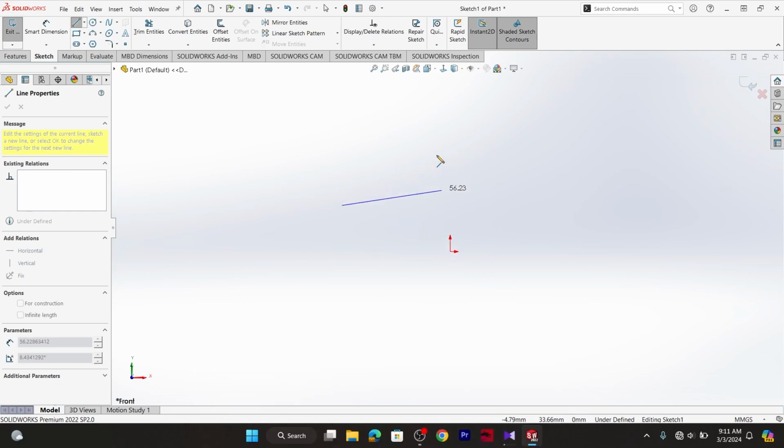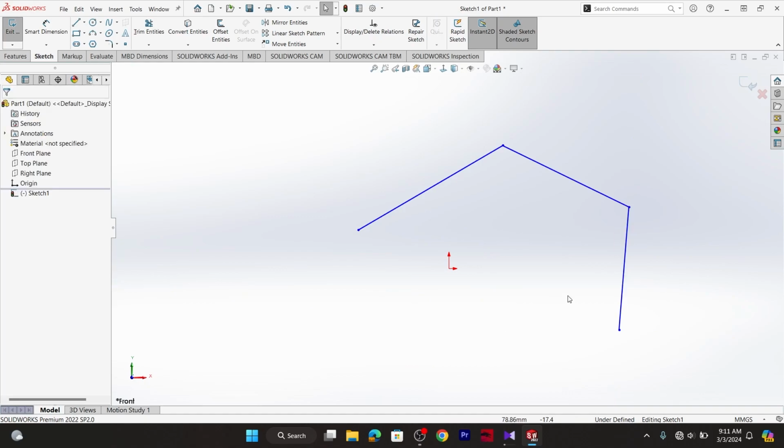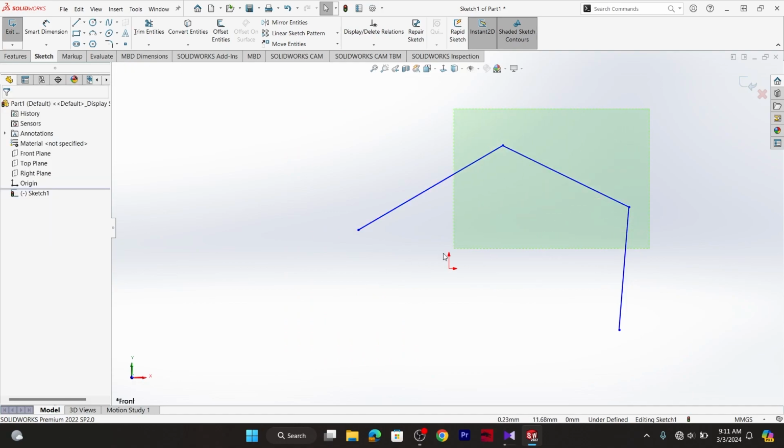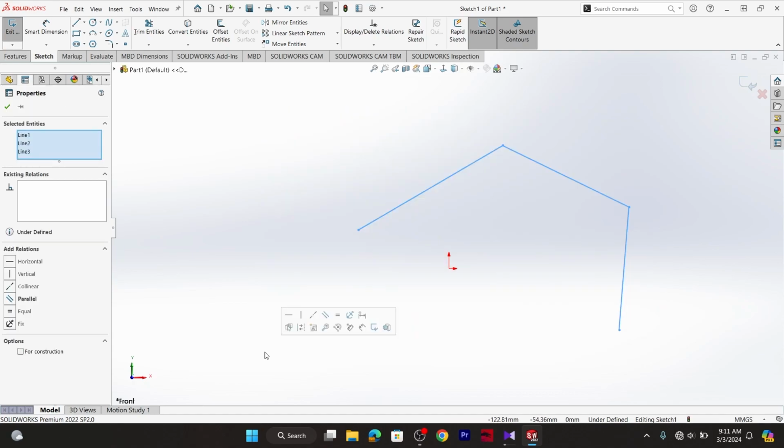If you click and hold your cursor, you'll still get a line, but it's not the required kind of thing, so you can click, let go, then again click, again and again, and you'll have your lines. Now, once you're done making your line, you can press the Escape key to exit out of the line command. Now let me select it all, and to do that, I'll just make a box. So this time I'll click and hold my left click and I'll make a window just by dragging my mouse, and now I'll press the delete key to delete everything that I have here.